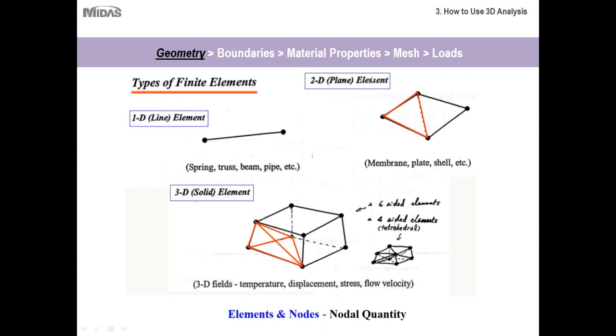Next, there are 2D or planar elements. These are the next level in complexity. As you can see, it's a series of nodes and lines that are connected, but within this frame there'll be what's called a surface. And upon this surface, you can model strains, displacements, and moments. So in addition to these edges and nodes, the surface can also be analyzed. This is typically used for retaining walls, as well as excavation types, and other flat structures that you can imagine.